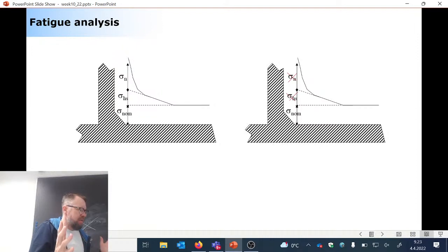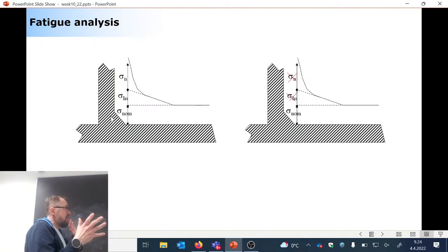When we conduct a multi-body simulation, we cannot figure out these very detailed stresses. These detailed stresses are needed if you want to use sophisticated fatigue life predictions. But we are unable to do that because we can only see the stresses that keep the structure in static equilibrium, but not more than that.